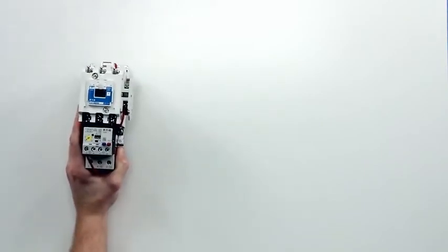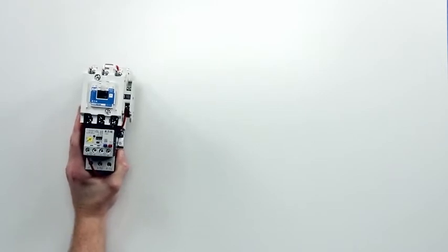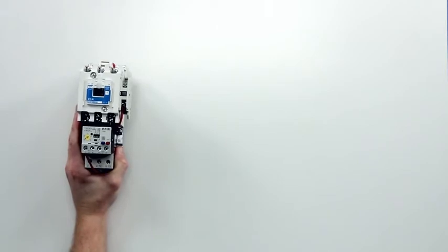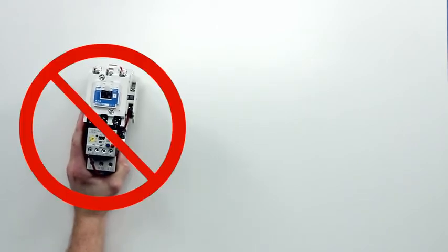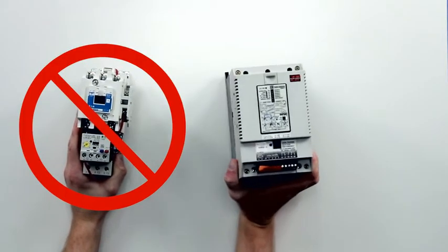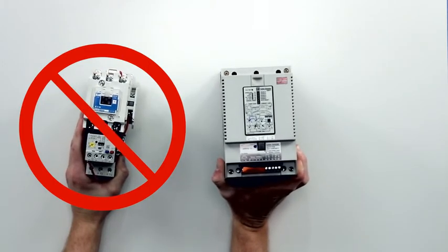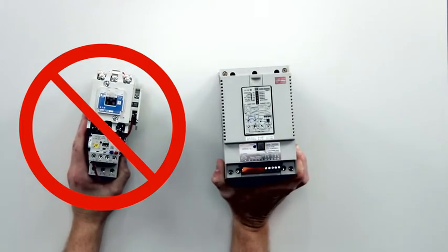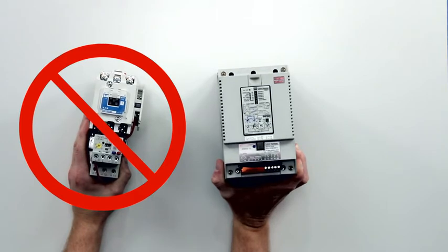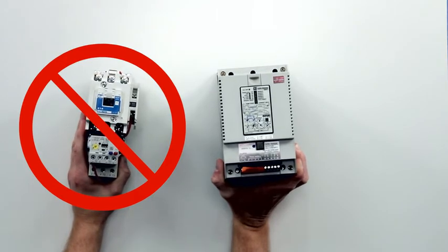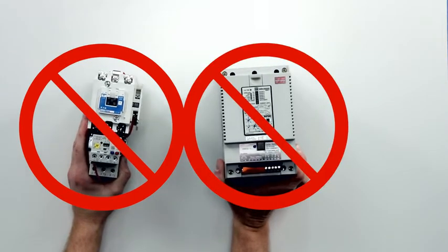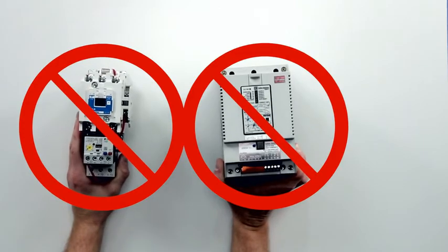Well, traditionally, customers use our trusty friend, the full voltage starter, which applies the full line voltage to the motor when it turns on. When a full voltage start is too harsh or accelerates too fast, we could use a soft starter to reduce the voltage sent to the motor and slowly ramp it up to full voltage. But with both of these controllers, once we get to full speed, the motor is stuck there until we turn it off.